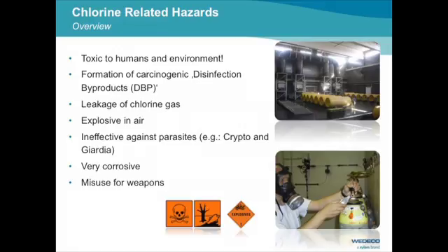And nowadays, people are a lot more concerned about the downsides of chlorine. Initially it was a good thing because public health could be protected by the use of it, but now people are getting more and more concerned about the hazards related to chlorine. Here is an overview of what people are concerned about. First of all, chlorine is a toxic gas, so if there are some leakages, it really can be dangerous for the people working with it.